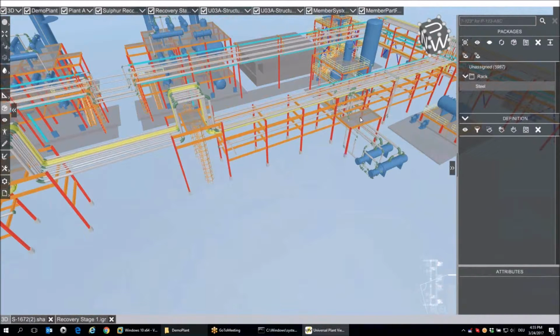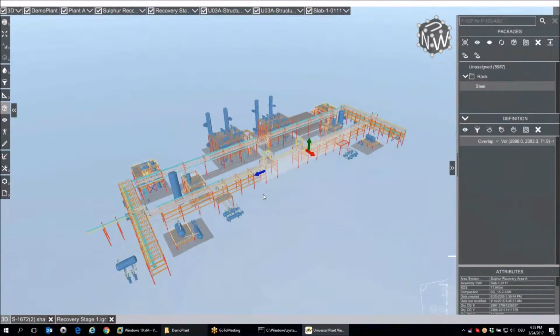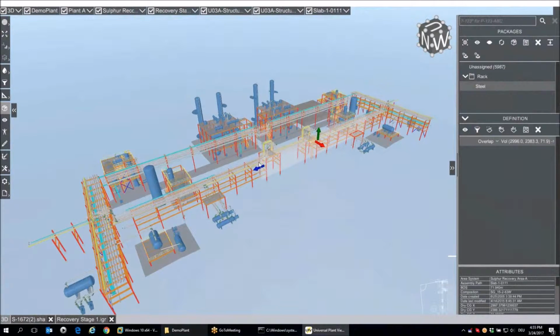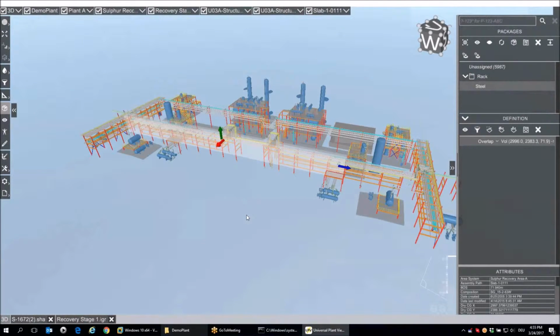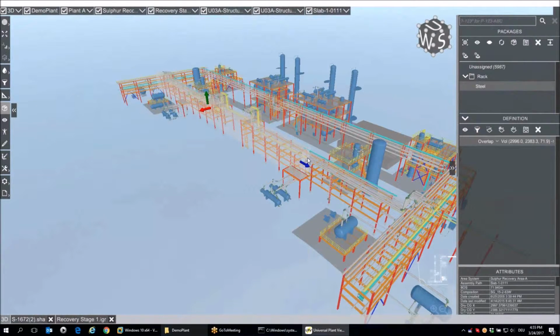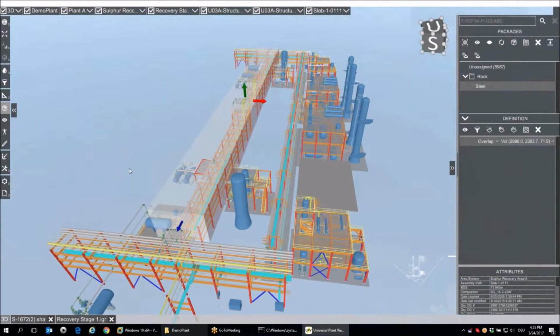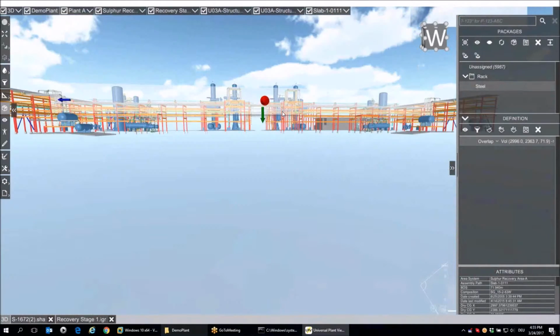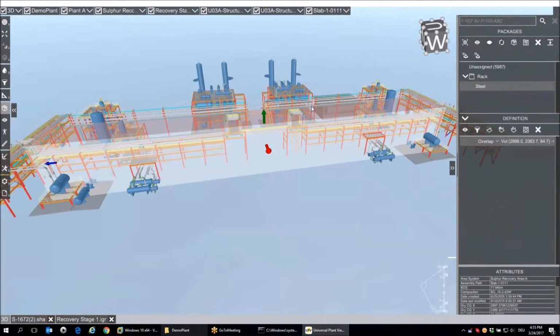So therefore I select any element, click on create volume, and from there I start to drag my volume to the right position. So maybe up to here, and on the other side I drag it up to here. That looks fine. Okay, I have to include the whole package here. Also the bottom I bring down, and I want to include all that piping.